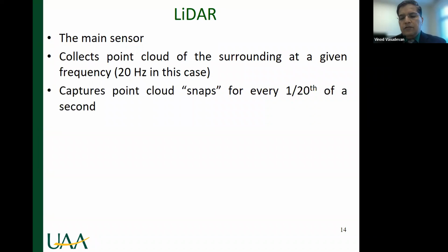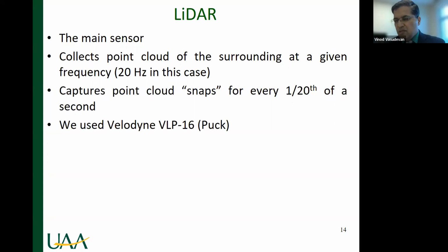So again, 20 Hertz means that you are capturing data every 1/20th of a second. That itself is sufficient for most of the traffic applications, but if you want a higher resolution, you can always choose it. We used the Velodyne VLP16. We also have the VLP32, but we used the VLP16 for this particular application.